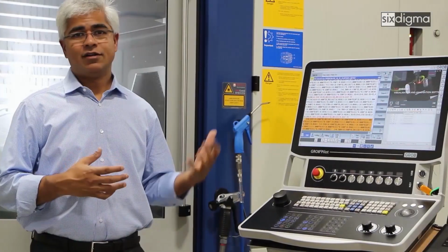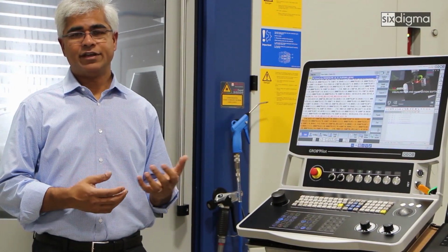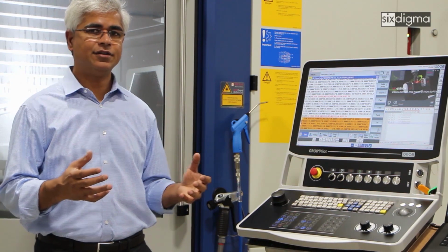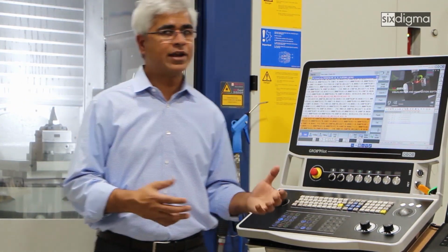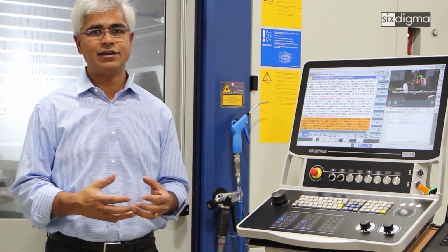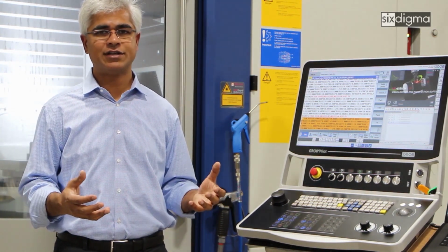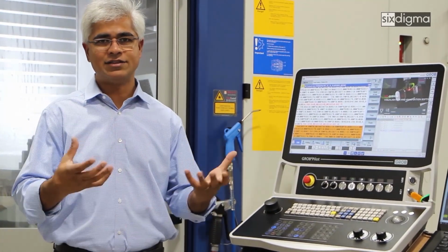So on top of a solid machine tool like the Grob 350, by bringing together the CAM, CNC systems, and post-processor, we are able to maintain very tight tolerances even on large parts. Typically, we maintain less than a 1/10 thousandth tolerance on a part that's about a few inches long, and less than 1/1000th of an inch tolerance even on parts about 3 feet long.